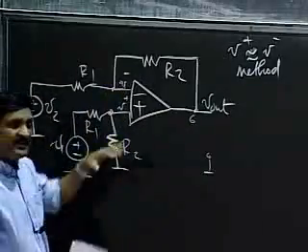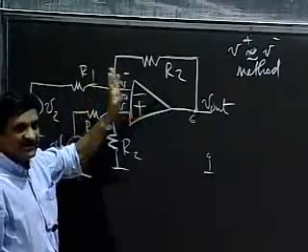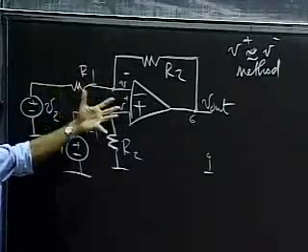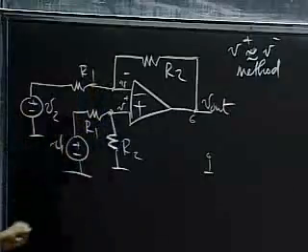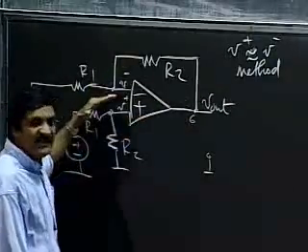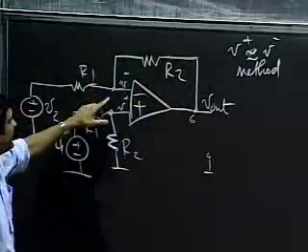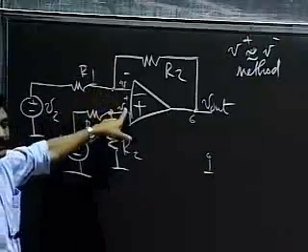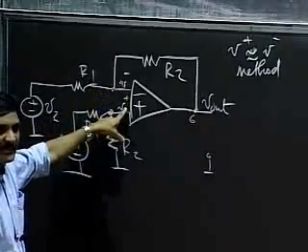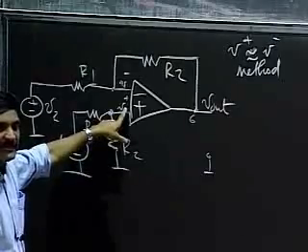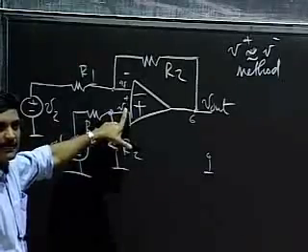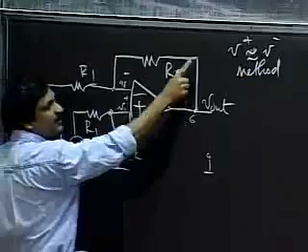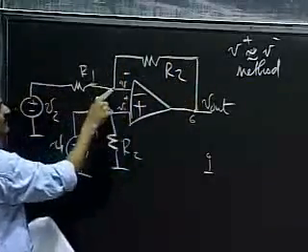So the key thing to observe is under negative feedback, when the op-amp is not in saturation, the property that V plus equals V minus holds. And the way it works is that it's not a magical property, it's simply that when I apply negative feedback, the negative feedback is such that it will force this V minus node here to be at more or less the same voltage as V plus. Remember, when in doubt, simply go back and think about your anti-lock brakes example we did last time. So if, for example, V plus increases, the output will increase, and so will the voltage here,